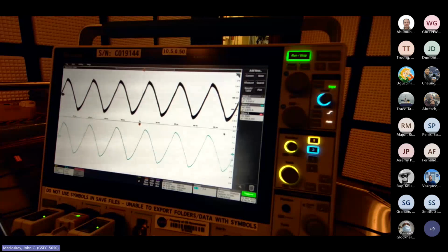So I had it set so that the AC RMS was right around 1 volt, but it's drifted up to about 1.18. So I'm going to take this down to minus 9.7 dBm. That's what, when I did this yesterday, that's about what I got.